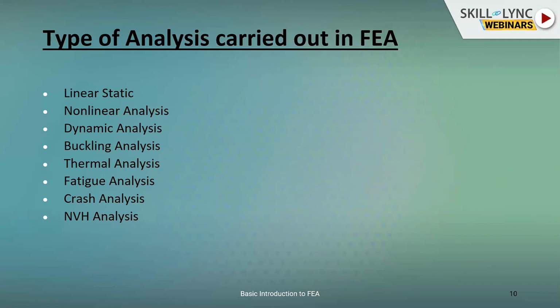And then we also consider the boundary nonlinearity. Meaning if the components are changing their contacts, we consider all those effects in this analysis. In this analysis, you can find a lot of convergence issues, and a lot of skill is required to perform nonlinear simulation. Then dynamic simulation is where the load varies with respect to time.